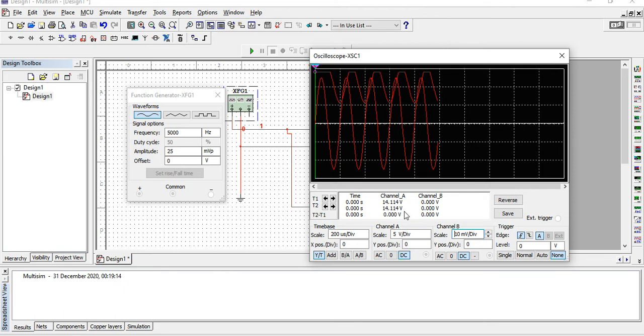So you can just write a value of 10 here, right? Okay, 5 volts per division is going, and accordingly you take the blocks. It's a 5 and it's a 5, so yes, 5 volts per division into 2 blocks roughly. So your voltage will be approximately 5 volts, right?